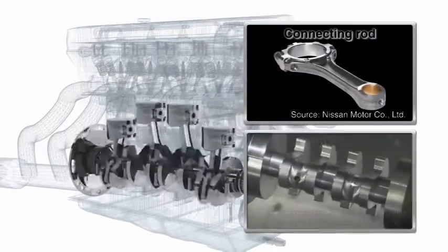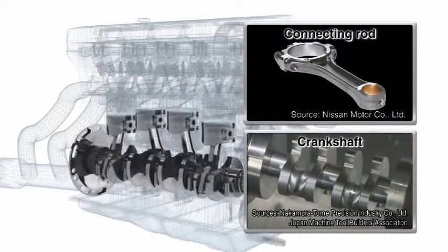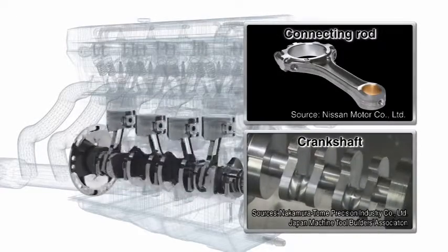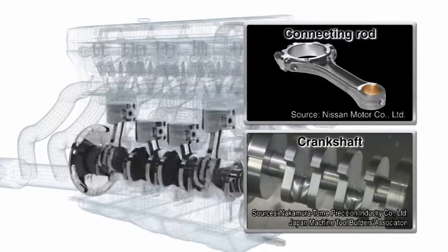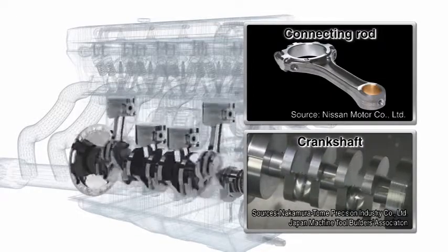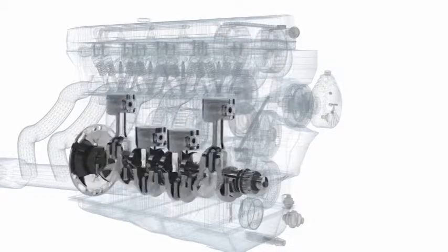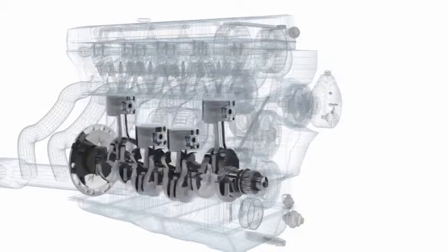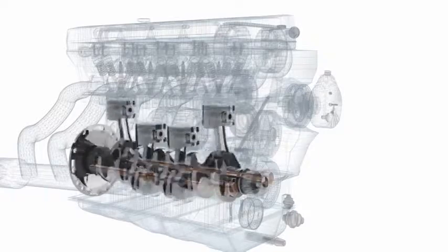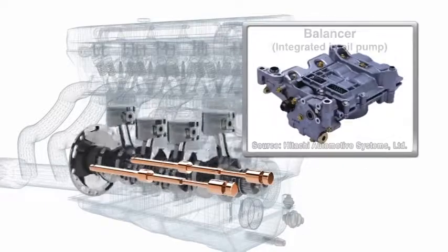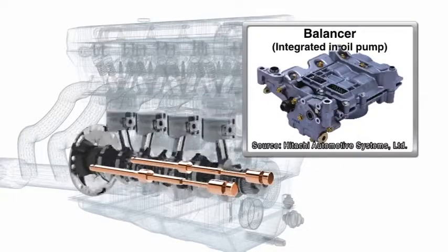The crankshaft converts the reciprocating linear piston movement into rotation via the connecting rod. The term engine revolutions per minute refers to the crankshaft RPM. The crankshaft vibrates vigorously during operation. The balance shaft offsets the vibrations to restore engine balance.